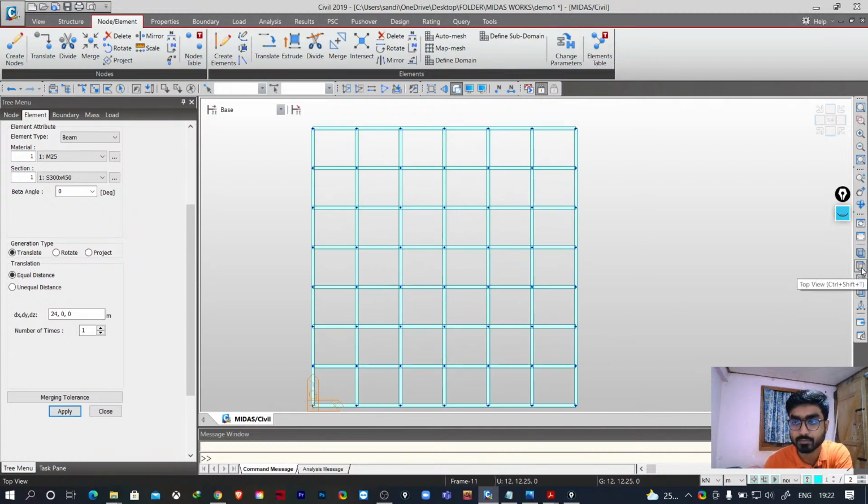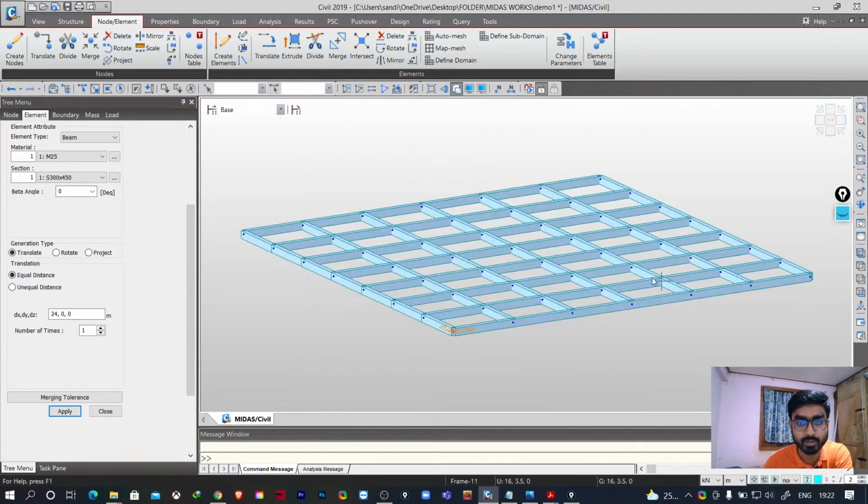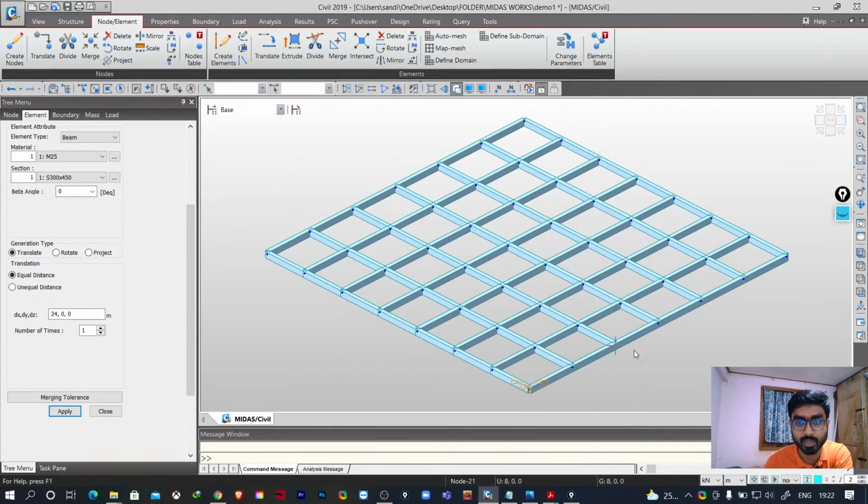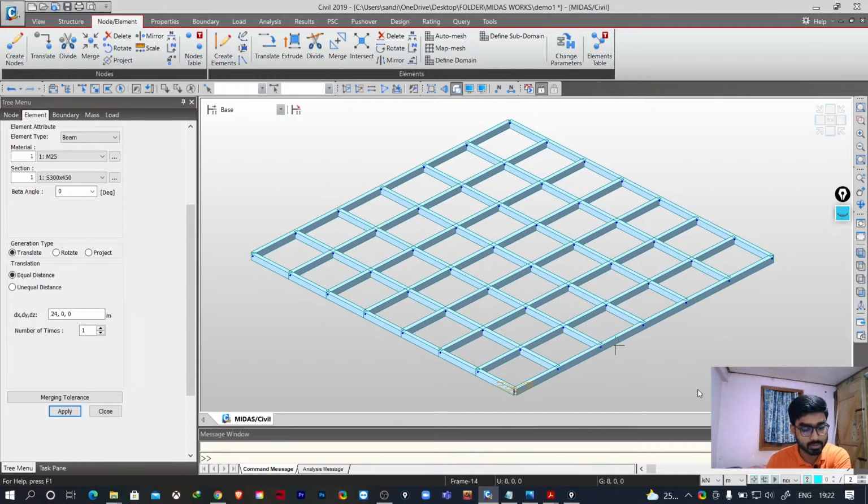You see here we have the isometric view. You can see the isometric view, or maybe from here. Okay, so this is how we can create the grid of beams. Now it is very easy, right? In STAAD.Pro or maybe in some other software like STRAP, we used to create models using nodes and elements, right? So here, if you want to create simple elements or some simple structures, you can create them using these nodes and elements always. Okay, and maybe some structures or structural elements that you do not have here to create automatically, then you can create them using these nodes and elements.